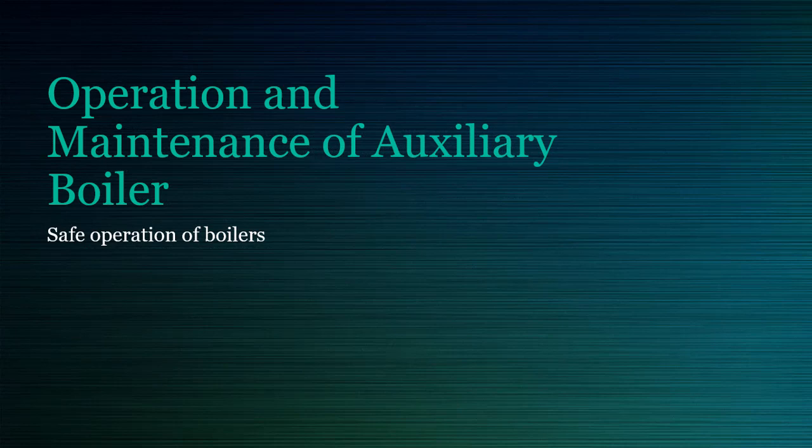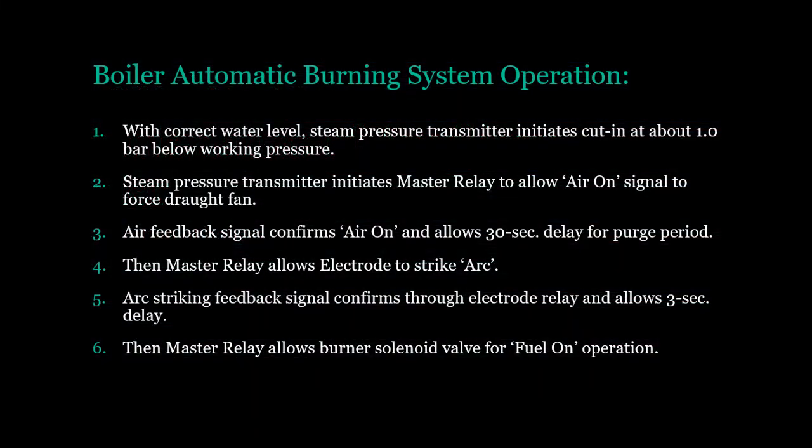Operation and maintenance of auxiliary boiler. Safe operation of boilers. Boiler automatic burning system operation: with correct water level, steam pressure transmitter initiates cut-in at about 1 bar below working pressure.